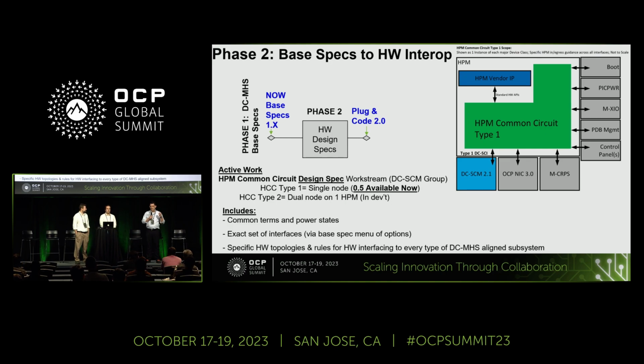What we're not trying to do, to a question that came up earlier, is create an approved vendor list of components on that HPM. It's rules around how you do the fan-out. Unlike in the MPIC spec, where we do have a table of approved connectors for every variation, we don't want to overly dictate which components people use. For example, the HPM FPGA, we know there's going to be 3, 4 variations of that, so we're trying to dictate at a logical domain how you would implement that regardless of which component you use.